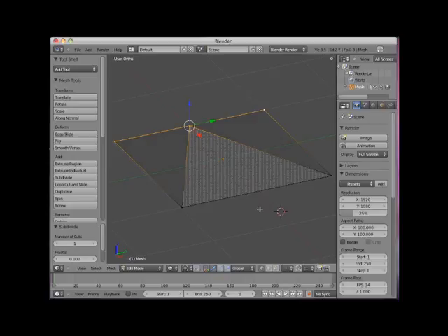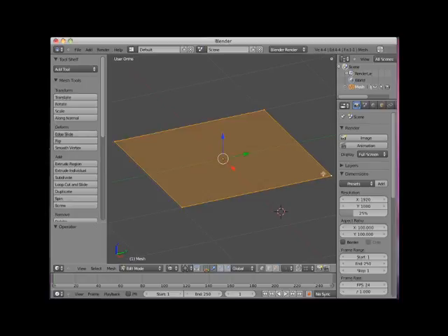I will undo the subdivide. I will add to this selection the bottom two vertices, completing the implicit selection of the four edges and thus the face. I will press the Subdivide button. Note that each edge is subdivided and new edges are created to justify the breakup of the existing face. In effect, the single face has been subdivided into four faces. I'll undo the subdivision.